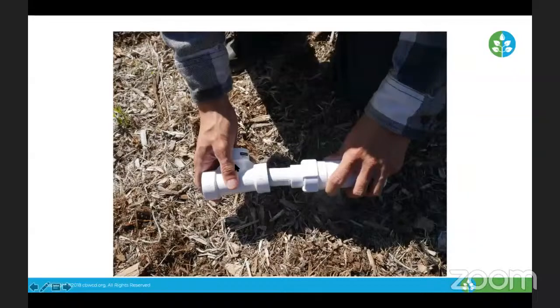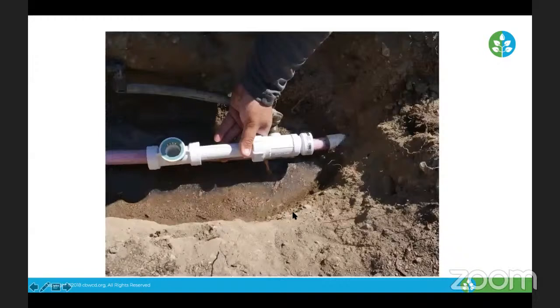This one in particular is a glueless option. This is PVC lock. If you're familiar with Shark Bite in the plumbing industry, it has double O-rings with little teeth. As you push the fitting onto the PVC pipe, it locks and it seals. It's without glue, but the same process would work for a glued slip fix.